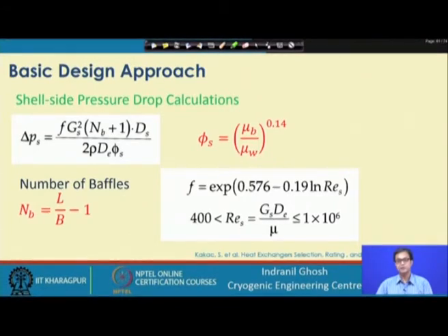Obviously, you will find that the exact number of 117 tubes will not be available. So, we take the nearest possible number of tubes which is close to 117, but it should be more than 117. Accordingly, there is a guideline, and for such a design we find the shell diameter, given in terms of single pass, double pass or triple pass and so on. Here in this case, since it was optional that we can choose single or double tube pass, so two tube passes,